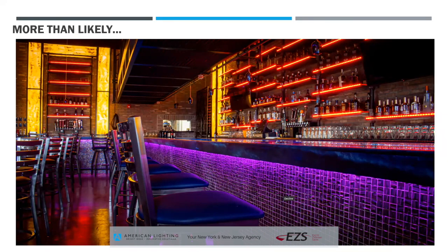That's where the RS-232 is really useful, because it allows you to give clear text commands. So you can say zone 1 dim up, zone 1 dim down, and you can do really complex stuff. If you're looking strictly to use those systems to send DMX through their integrated DMX capabilities, you'll have to use an RS-232 to DMX interface. And in that situation, Prism would not apply controls, but we would strictly apply DMX devices and decoders. Does that answer your question?